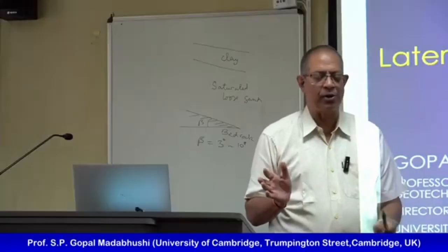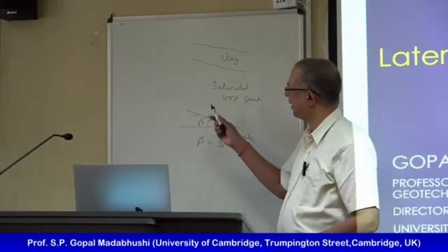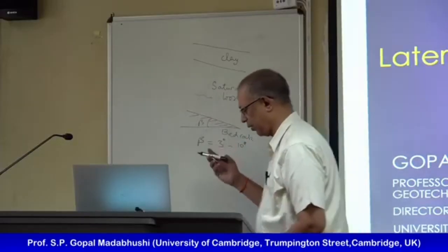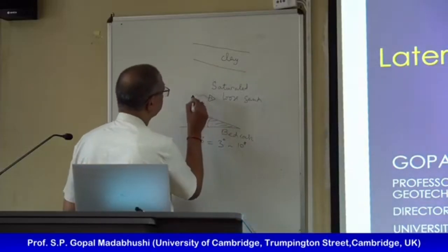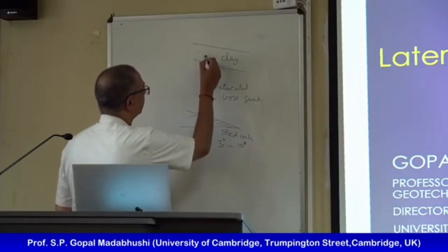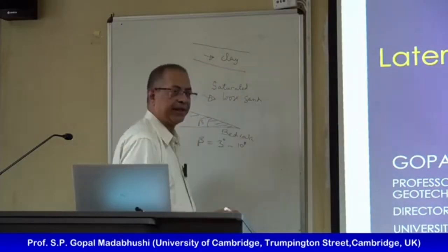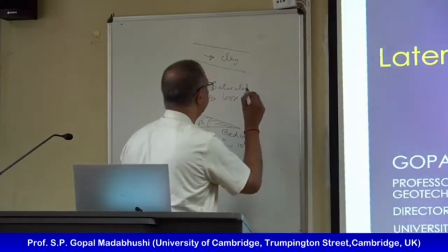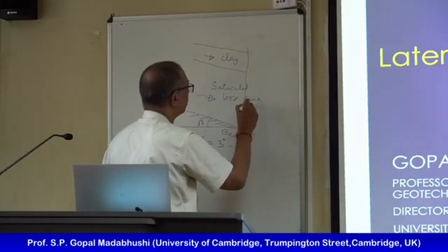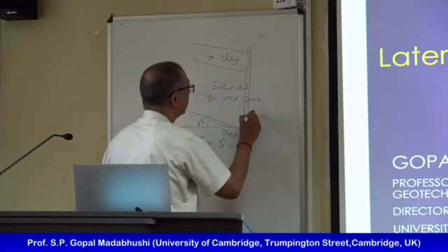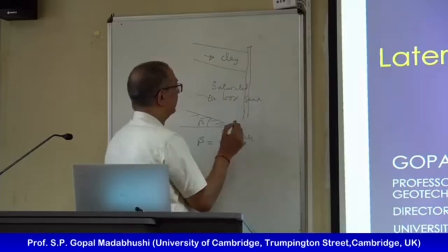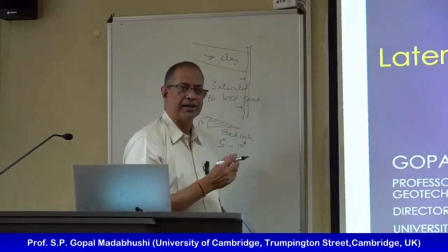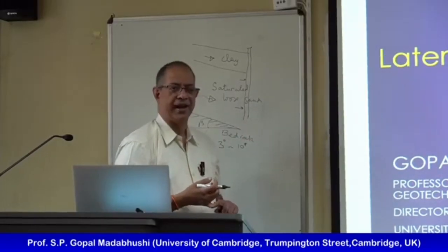So everybody thought it was all great, and then when the earthquake happened, obviously this stuff liquefied and moves along this direction, but as it does, the clay also goes for a ride with it. Now the problem is, if I imagine a pile going through here, I'll get some amount of lateral pressure on this. That's the first problem. How do we estimate that?